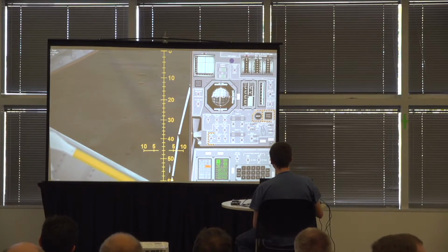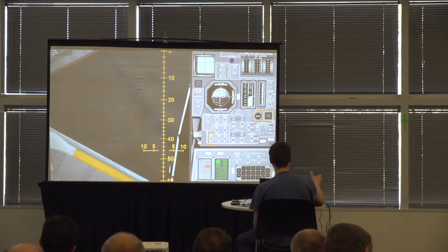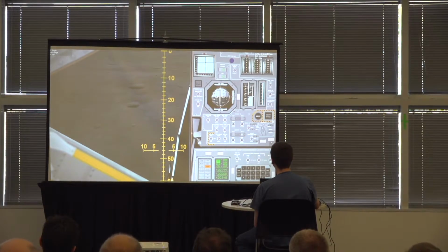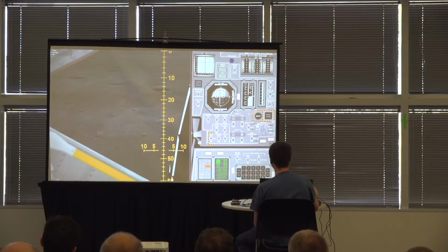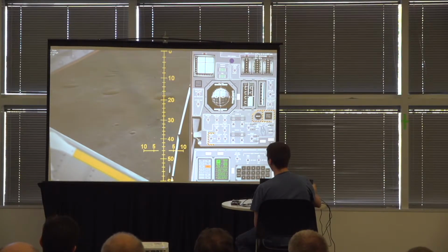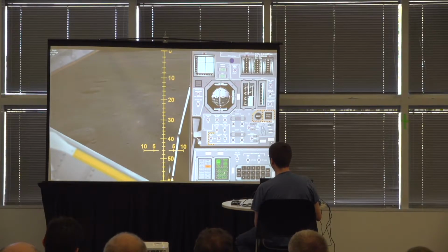The way I did that, AGC and attitude hold, which again just gives me control. I can pitch the LEM around as I want. And then I have what are called rate of descent switches, ROD switches. Every time I press one of these two buttons that I have mapped to my joystick, the AGC slows my rate of descent by 1 foot per second or increases it by 1 foot per second. So in this mode, I'm controlling the attitude and through that my horizontal velocity, and the AGC is controlling my vertical rate to the number that I have set into the middle register here with my rate of descent switches.